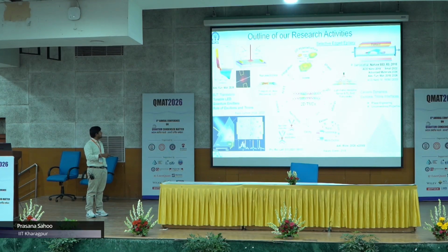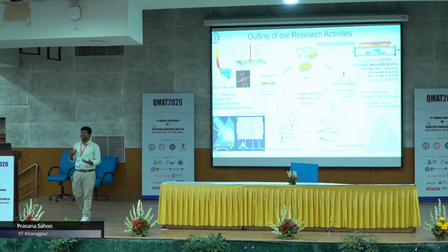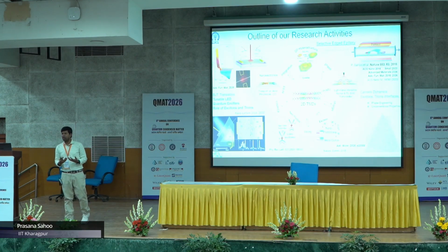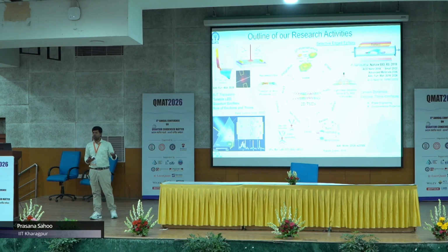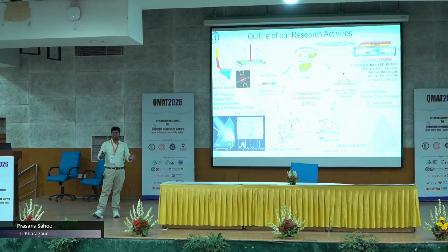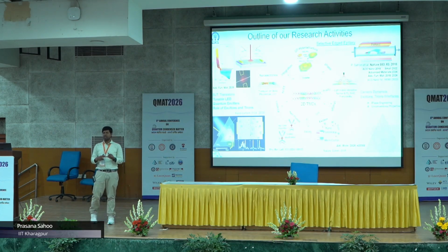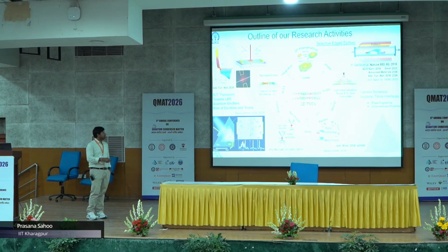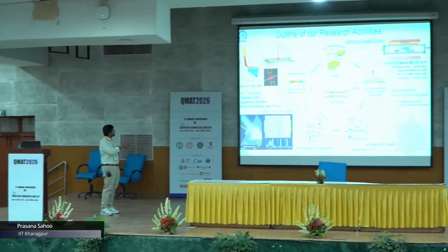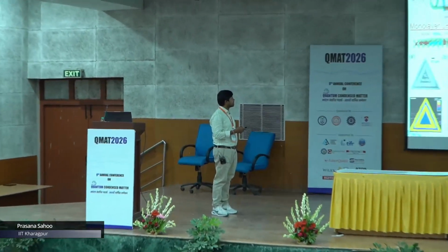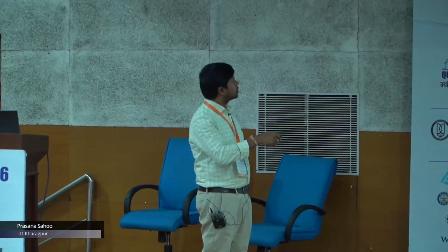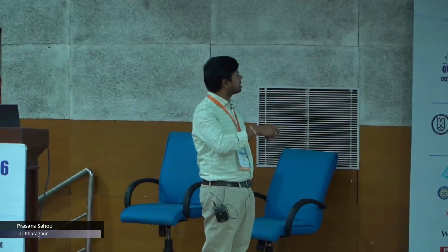Another important aspect is that this material we grow directly grows as a P and N type semiconductor, which gives a lot of opportunity to do optoelectronic devices, because PN junction diodes are fundamental to many applications including LED, solar cell, photovoltaic, and laser. Many more can be expected from this kind of combination when probing in device geometry. I'll explore that. Just to show that this kind of material can grow, it is selenide based, with Raman and PL mapping.